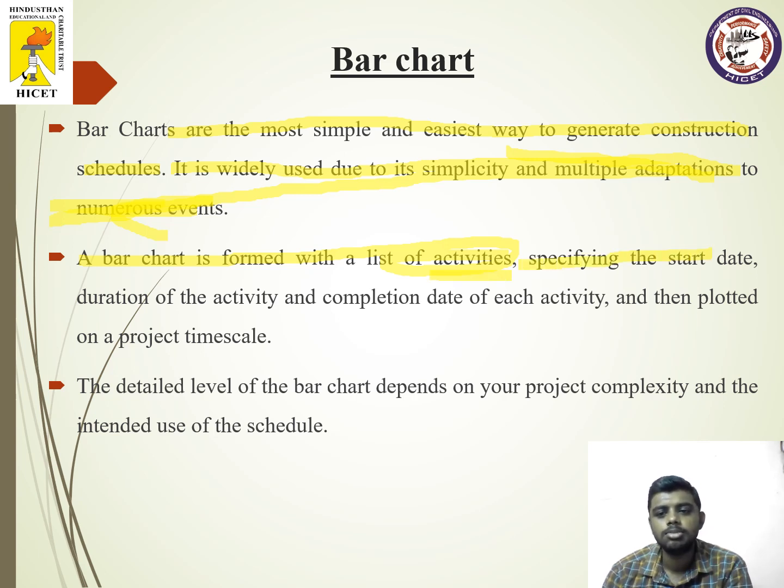And the next one is specifying the start date. If you are going to start a project at a particular date, you can actually specify the date, so the real life comparison can be done. If I have started my project and it is the seventh day of my project, I can actually check with my calendar what the date is today, whether I'm going according to the schedule, whether my schedule is correct or not. Everything can be checked.